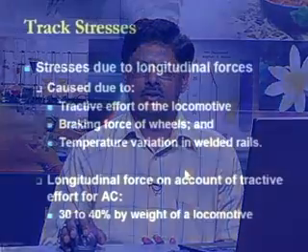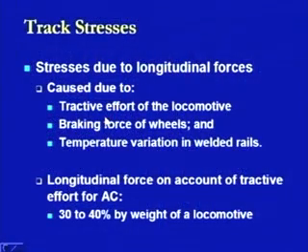Now, if we look at the first condition where the tractive effort of any locomotive is being considered, that is the total amount of effort which is being induced by a locomotive, as we have discussed in the previous lecture also, where this tractive effort is found out on the basis of the resistances being computed and the friction being induced between the contacting surfaces. On the basis of this tractive effort, what we found is that the longitudinal force on account of the tractive effort is something like 30 to 40% by weight of a locomotive. So this is the amount of force which will be there in the longitudinal direction.